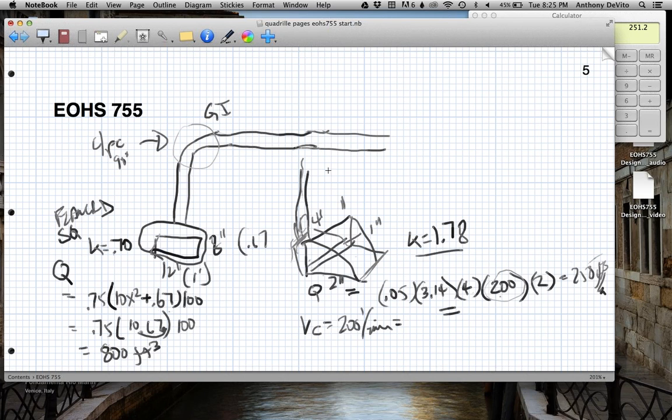Now we have a duct going up here, and now we want it to join the main duct. So we are going to have a junction, or a T, that's going to look something like this. It's going to start out narrow. It's going to get a little wider because we have additional air that's going to join this. And this junction is going to have a specific angle. What angle should we give the junction? Smaller, okay, let's give it 30 degrees. The smaller the angle, the more it's moving in that direction anyway.